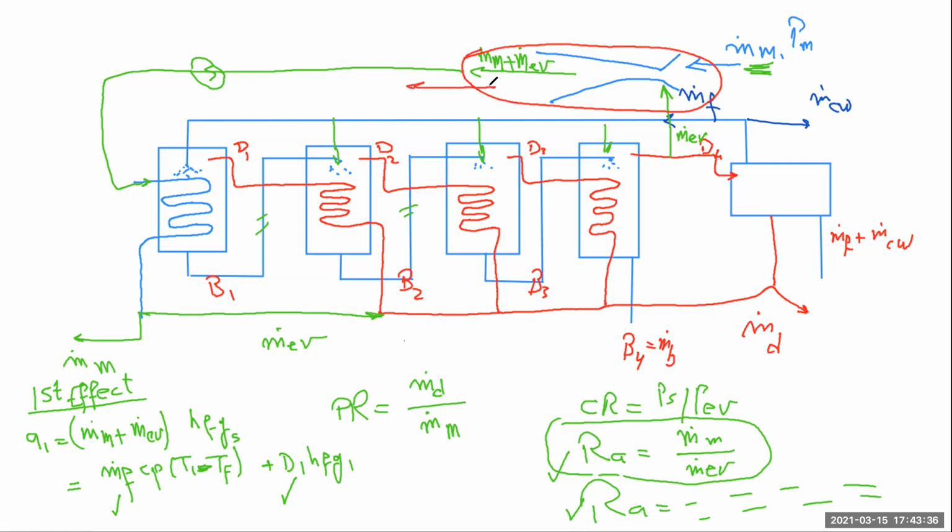and shift it forward? And instead of extracting the vapor from here, why don't we extract it from here? Or from here? Or from here? Why necessarily the fourth effect or the last effect? Typically, we are talking about an 8-effect system in the industry.